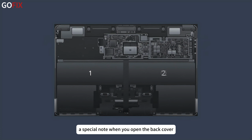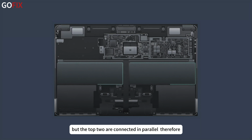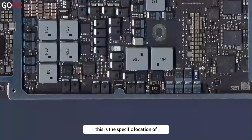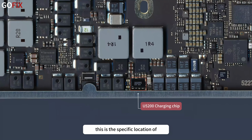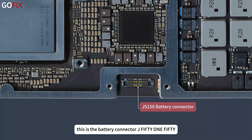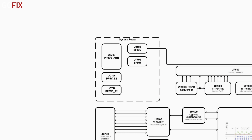A special note, when you open the back cover, you will see 4 battery cells, but the top 2 are connected in parallel. Therefore, the battery pack's output voltage is still that of 3 cells. This is the specific location of U5200 on the motherboard. This is the battery connector, J5150. Before starting any motherboard repairs, you must remove the battery plug from this connector to cut power to the board.